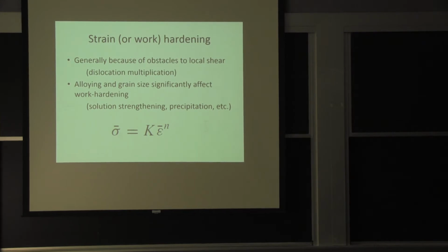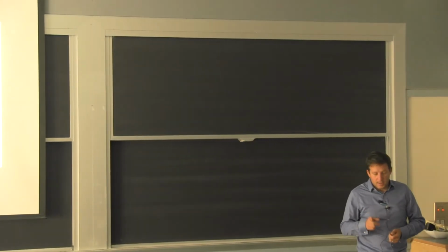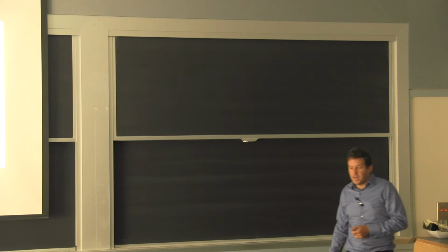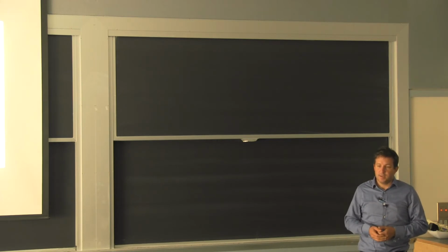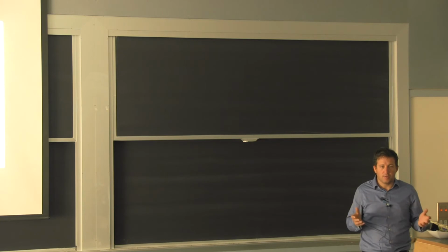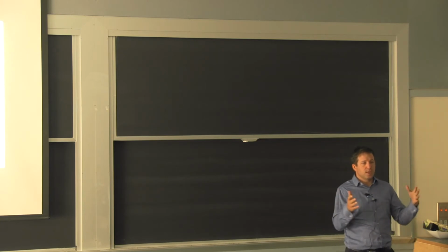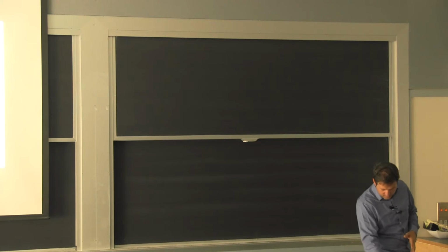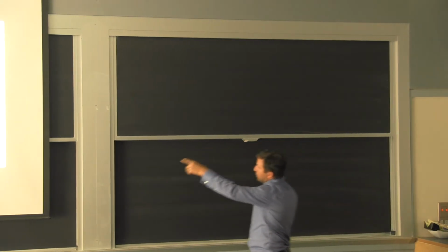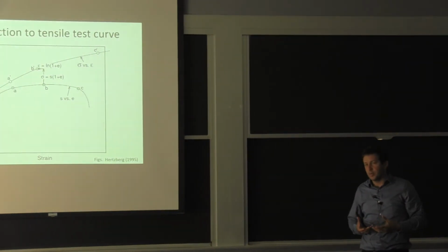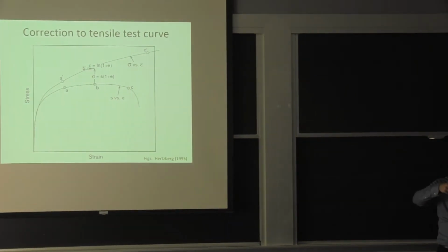It's very useful because it prevents us from having to do very sophisticated experiments where we'd either study what's going on in the neck or load the material in bending or in compression in a way that we don't get the neck. The necking in the tensile specimen just really comes as an instability. It's a geometrical effect. If I do everything in compression, I would right away get the curve that goes to the C prime going up, because I don't have the formation of that neck. There's no kind of buckling phenomenon.